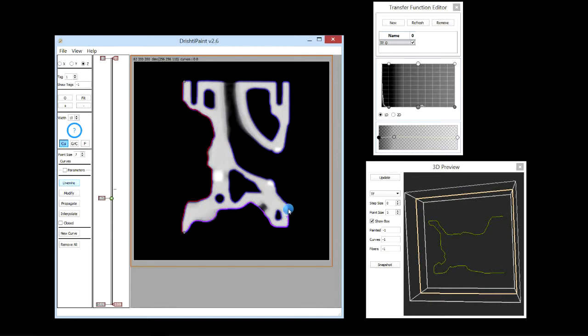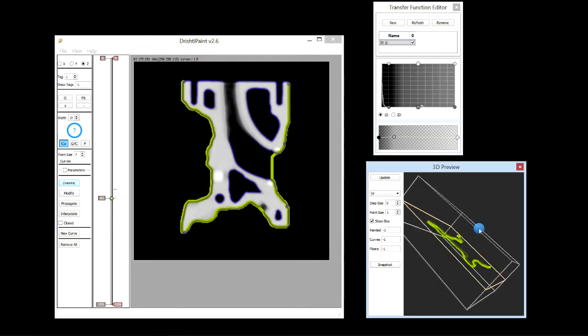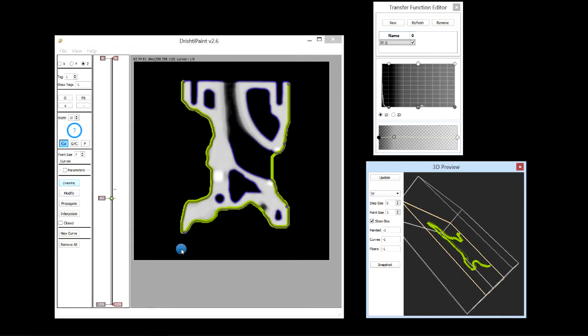So if you go to another slice, let me set thickness to 10, and let me just select the live wire again, and then press spacebar to finalize this live wire or freeze it. So you get a curve of width 10 straight away. So the thing is, if you want to change the width later on, you can do it. That's not a problem.